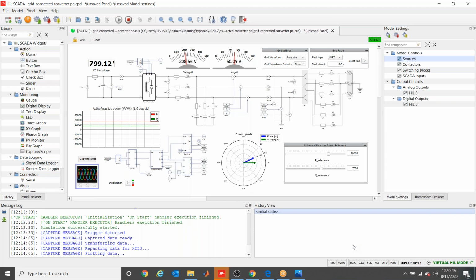So no resources from our laptop will be used when the HIL is running. Exactly, no resources will be used from our laptop or computer. At that time, all the resources are being used from our real-time simulator. All the calculations and all the data processing are being done by our real-time simulator, not by our laptop. But when you are doing only simulation, whatever you have developed will be performed by our system CPU, meaning whatever Intel Core processor we are using in our laptop, it is performed by that only.